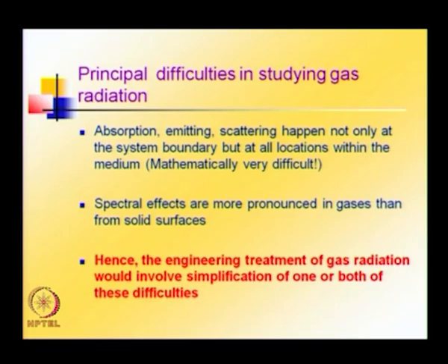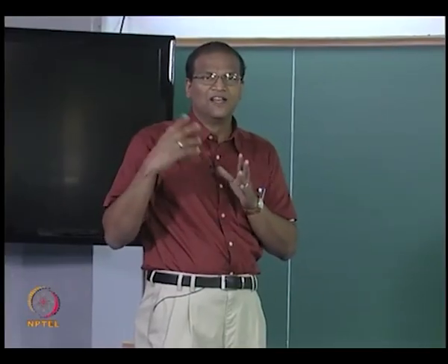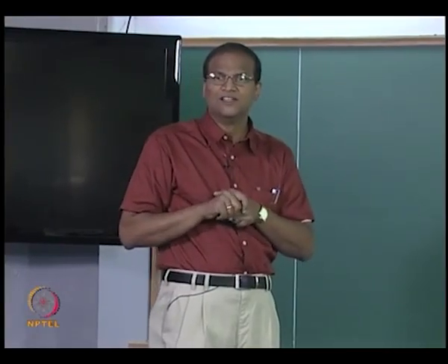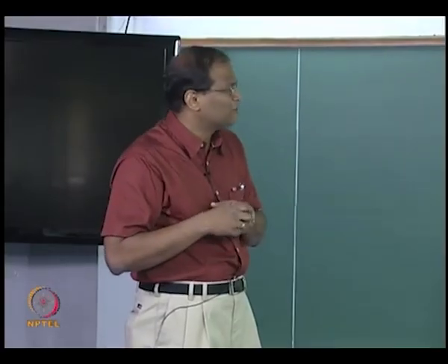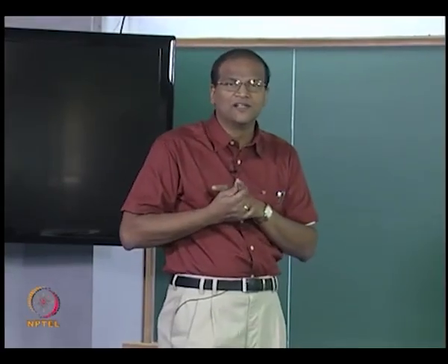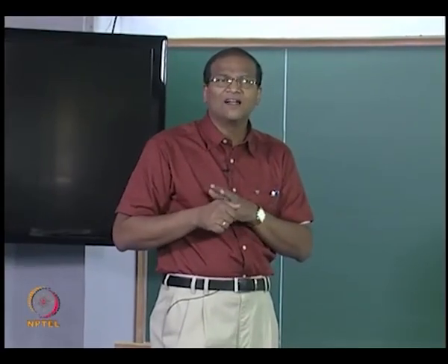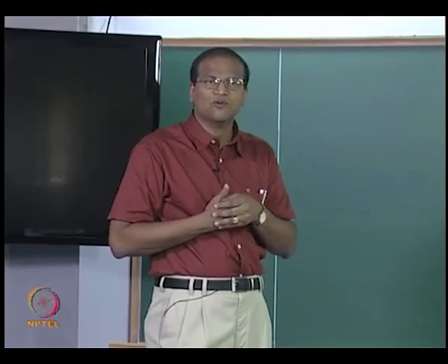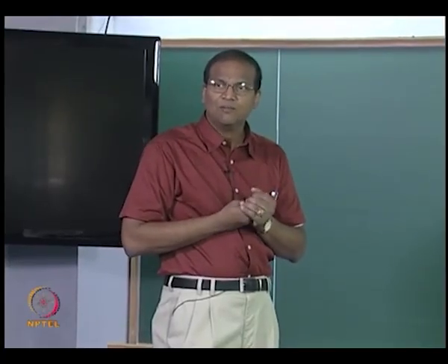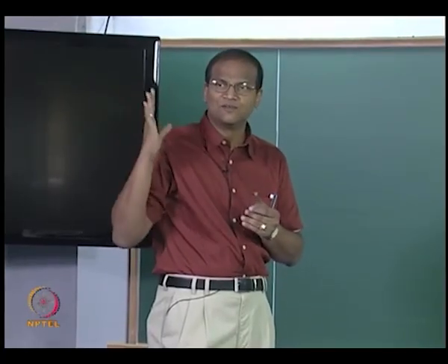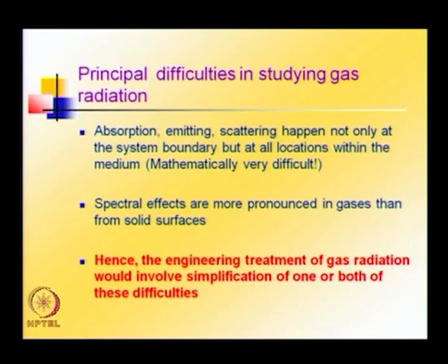Azimuthal, zenith, all angles have to be considered, and this fellow may behave differently, it may behave crazily in different directions, though these have to be accounted for. Spectral effects are more pronounced in gases than from solid surfaces. This grey gas assumption is more a myth than a reality, but for many surfaces we put grey diffuse and proceeded, isn't it, in the last 1 month. Hence the engineering treatment of gas radiation.